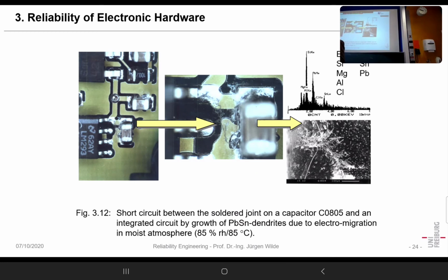In fact, I presently have a PhD student at Bosch who is precisely addressing the conditions leading to such tin tree formation. So that's really an important problem. Partly it can be avoided by putting on a conformal coating, a varnish on that board, but that only partly solves the problem, because water also diffuses into the polymer and then precipitates under the polymer.